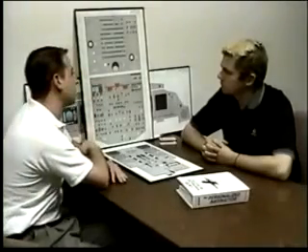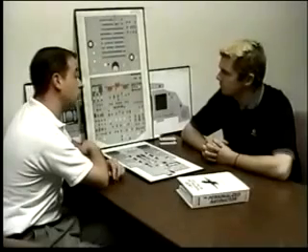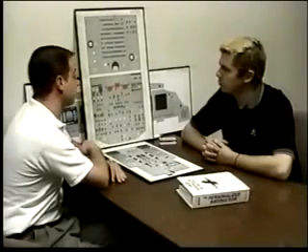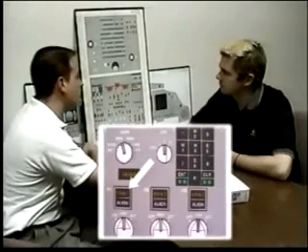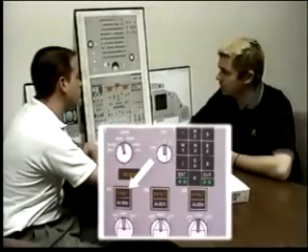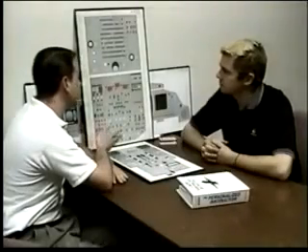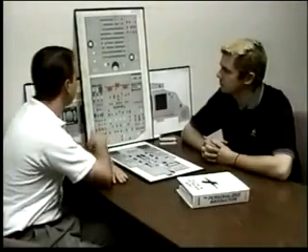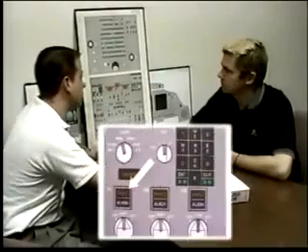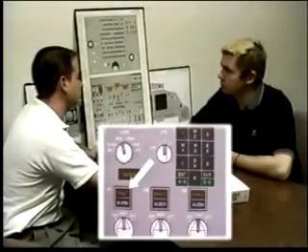You lose the captain's attitude and heading. What's failing? The IR, number 1. You look at the overhead and you see a flashing fault light on IR1. That indicates to me that heading and attitude may be recoverable. Same scenario, you've lost attitude and heading, but this time you look up and it's a steady fault light. That means the IR is kaput.